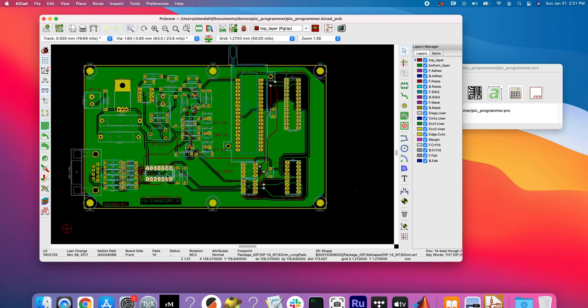If I click on a particular component, so this is clearly an integrated circuit socket that would go in here, you'll see that it brings up a bunch of information about it. Component number, U again, is often used to refer to integrated circuits, so U2 happens to be a 74HC125. Tells you when it was changed. It goes on the front of the board, has 14 pads, you can tell that's true. Note the typical convention, which is that pin 1 gets a square, whereas the rest get an oval.